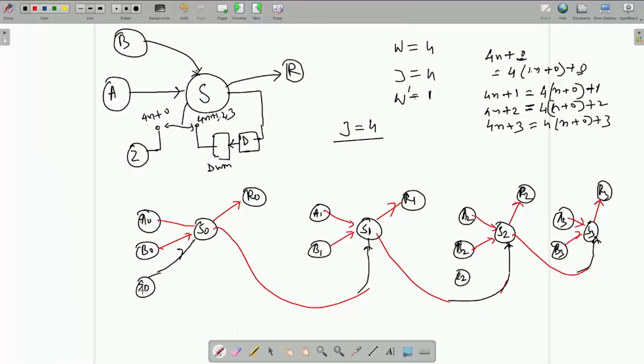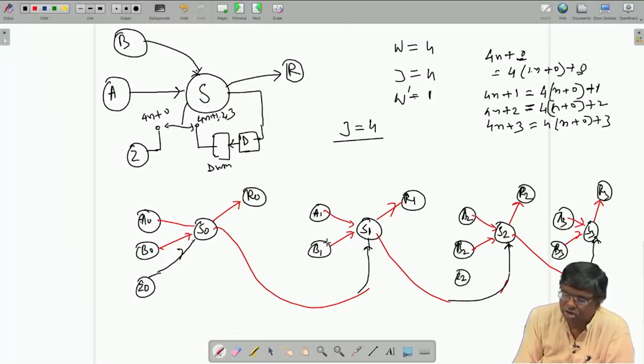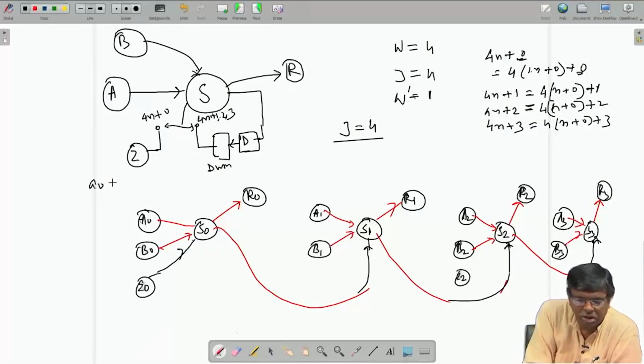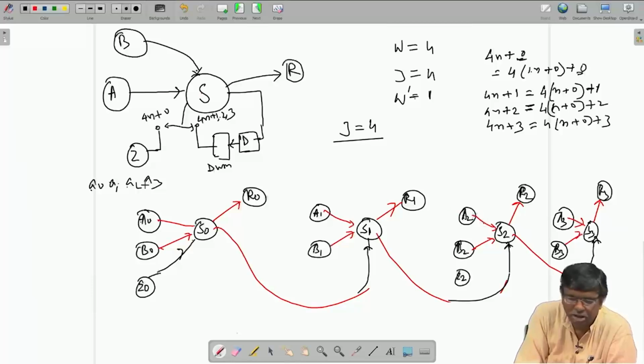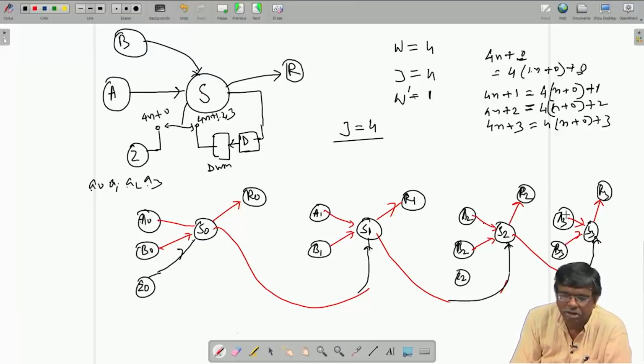So, A0, B0 with initial 0 carry, the result and new carry go in, as this carry goes in as carry input for A1, B1, okay. Then the next 2 bits, because A0, A1, A2, A3 in any cycle, this will go here, small a1 will come here, small a2 will come here, small a3 will be coming here, same for B. So, now in the same cycle, because they are parallel, A1, B1 get added here, all right, A2, B2 get added here, they all get the carry from the previous addition, and you get the result. This is nothing but your 4-bit full adder.